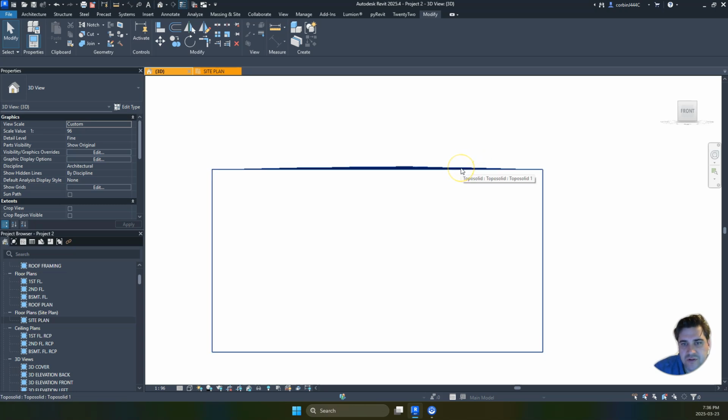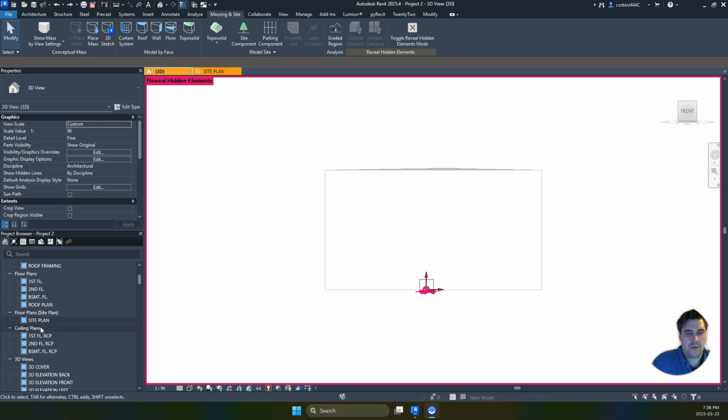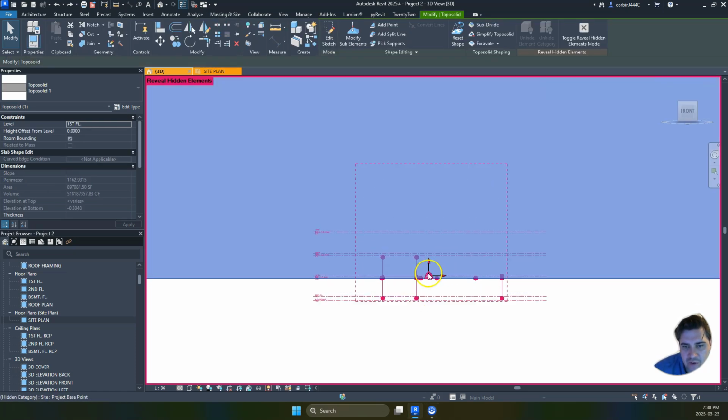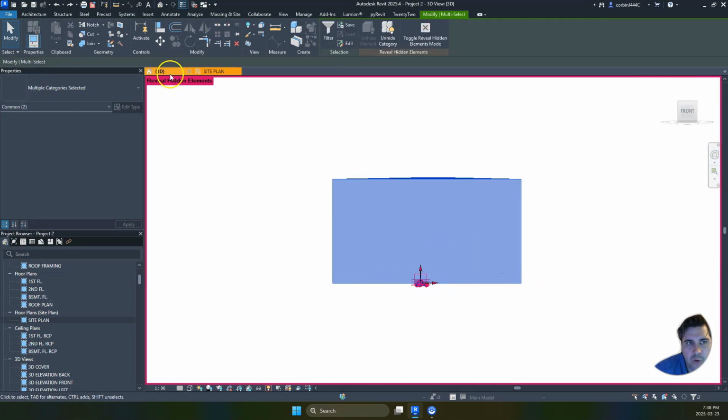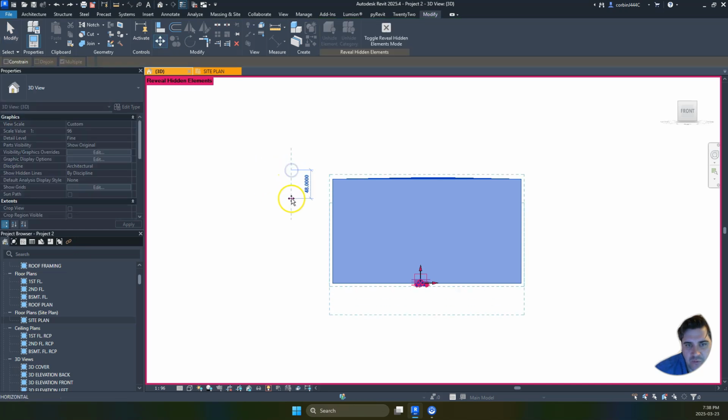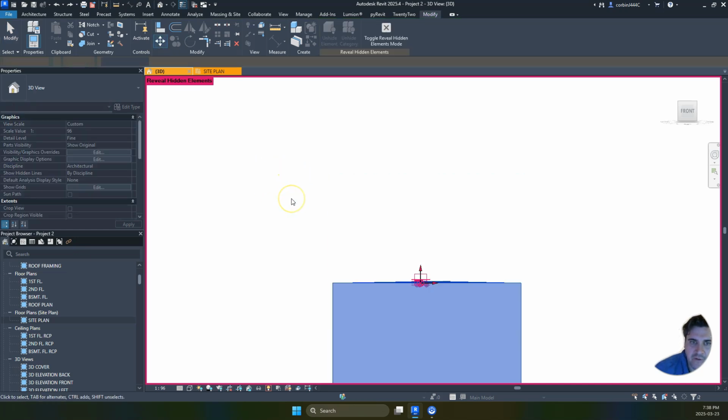And so what we're going to do here, I want to lower our topography and our survey point. And so if we tab over this, we have the triangle one. We're going to lower both down by 175. So we're going to drop these 175.